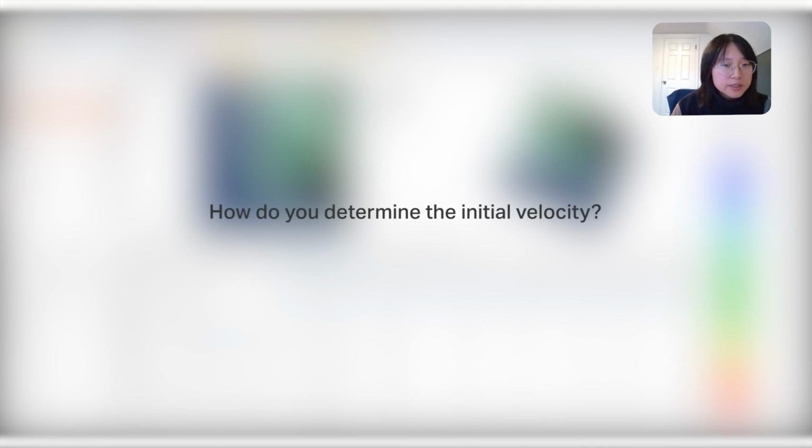To determine the initial velocity, sometimes people have field data if they're using some sort of instrumentation. So that's one way to approximate it. But if you don't know, you can start with 0, or put in a mean value and apply a distribution to that initial velocity, which will create a spread in your rockfall runouts and end distributions.